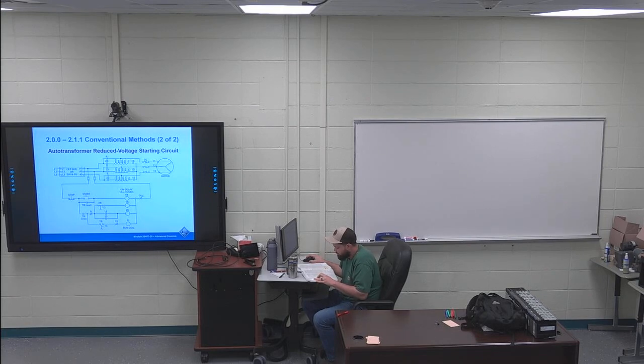Simultaneously, the normally open timed close contacts of the timing relay TR close, causing R, the run coil, to energize. Its power contacts close. So once my R coil comes on, my power from my circuit breaker or fuse just runs straight to the motor.